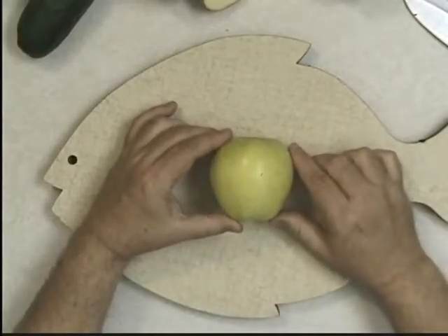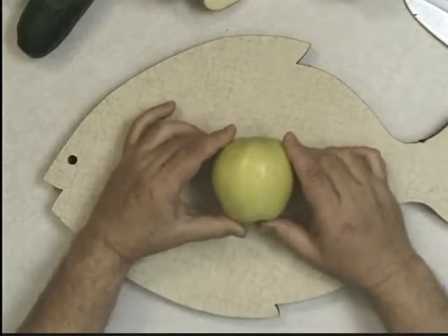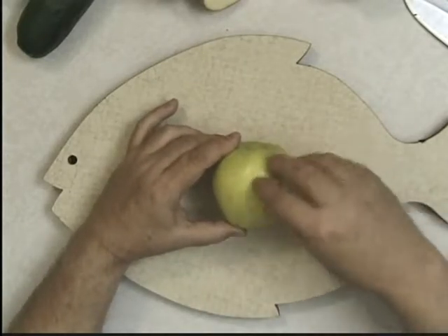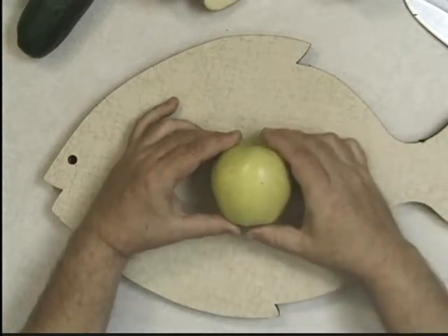Another type of section view that I want to illustrate is called a broken out section. There are times when we have objects where a full section is not what we want to do, and a half section doesn't lend itself, or a revolved section doesn't lend itself, but we just want to break out a small chunk to reveal just the interior details in a certain area. Let me illustrate for you a broken out section.